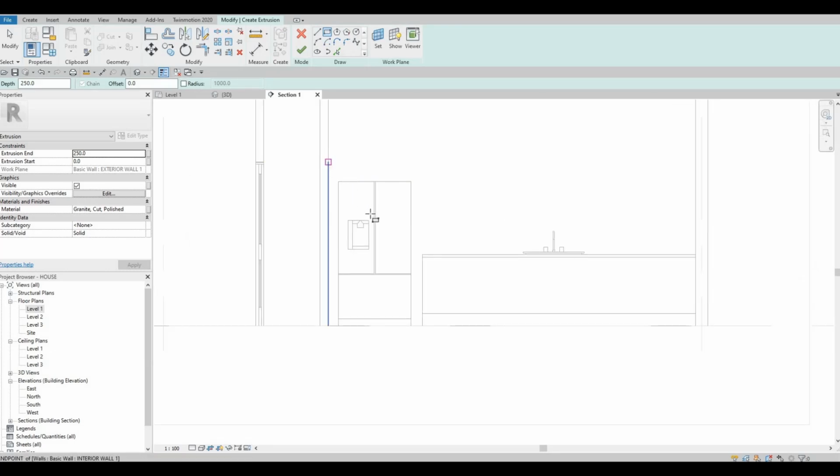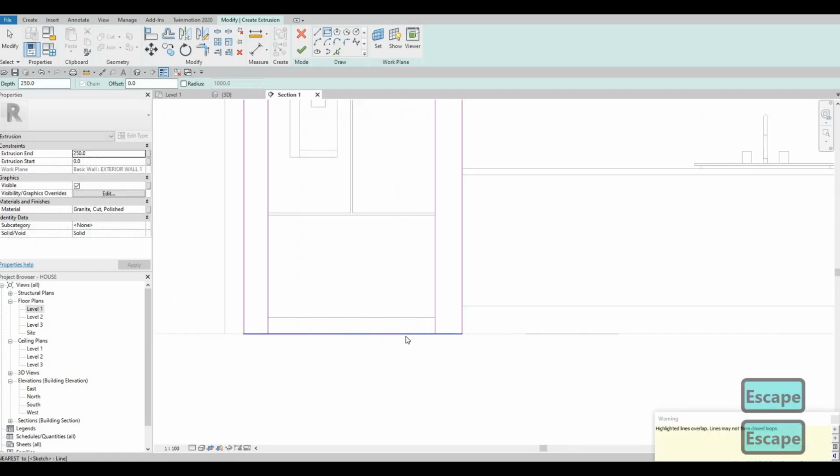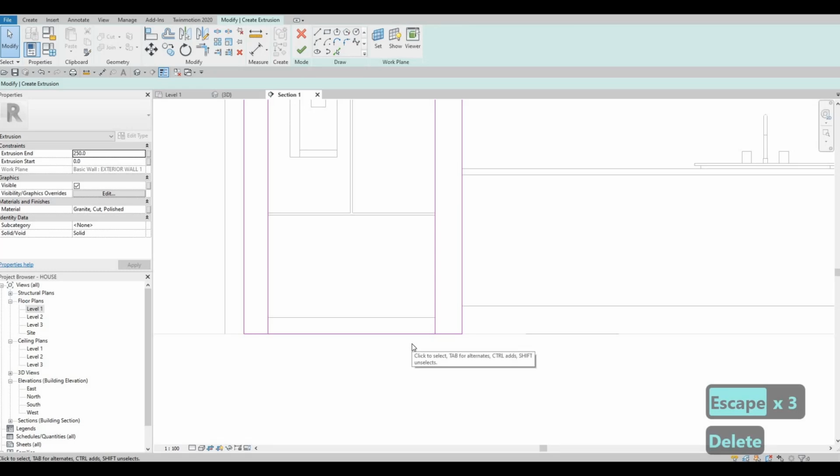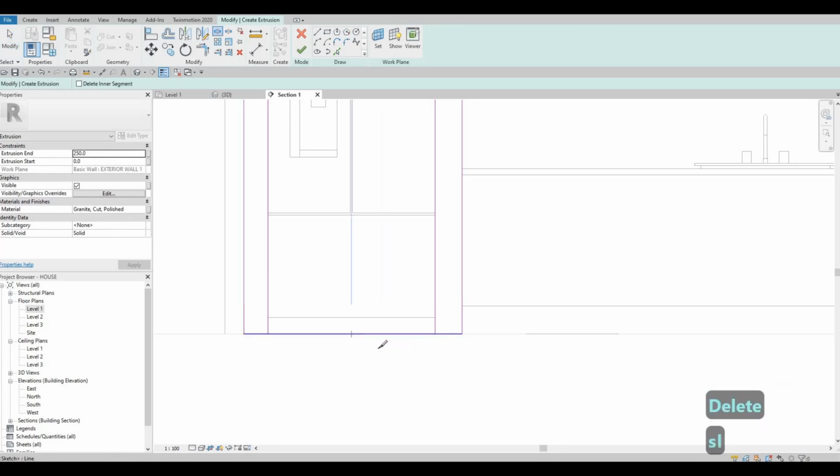After that, let's use rectangle to create this, and then delete this. And then slice this. So SL, split element. Press escape. TR, trim and extend. So that was trim and extend. And then SL for split element.